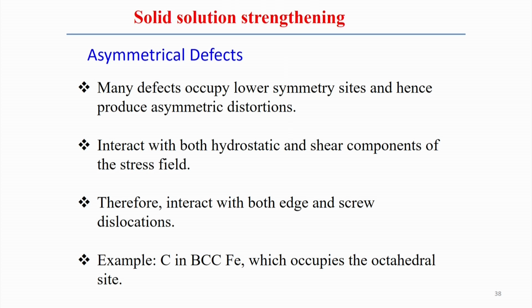When substitutional or interstitial atoms take that lower symmetry position, they try to create an asymmetric distortion field. Therefore, they interact with both the hydrostatic component and the shear components of the stress field. So both components are present there, hydrostatic and shear stress field.